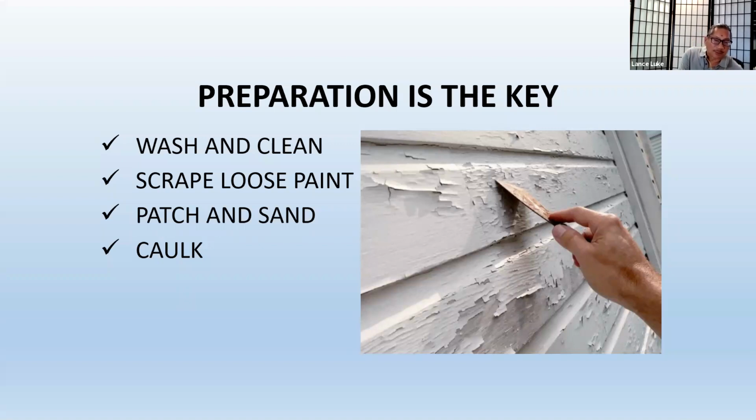Okay, so the patching and sanding is important, but you got to use the correct sandpaper. And I've seen situations where the contractor is sanding crown molding or ornate custom-made stair hand railing and pickets on a multi-million-dollar house that's made out of koa, custom made, and the worker is using coarse sandpaper to sand it before they put their clear coating over it.